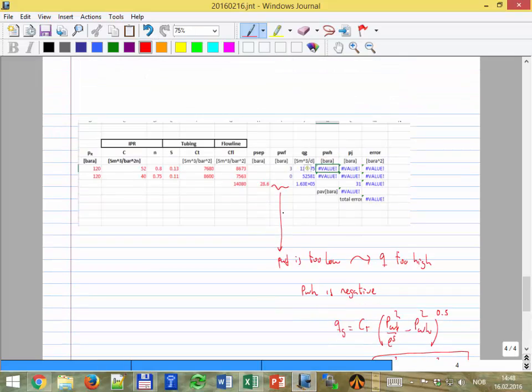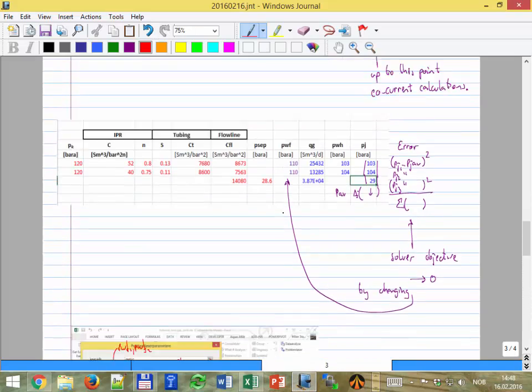That I think I put here. Okay, you create an average junction pressure, then you take the junction pressure calculated from well 1, calculated from well 2, and calculated from the pipeline. Then you subtract from this average pressure. Okay, you square it because you want all the terms to be positive, and then you sum all of them. And this is actually the objective that I'm giving the optimizer.